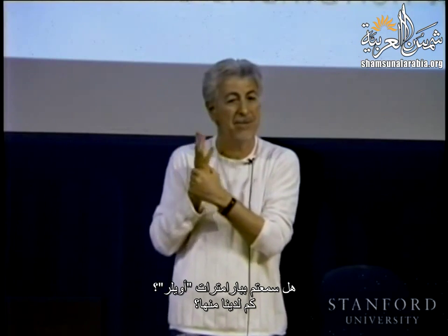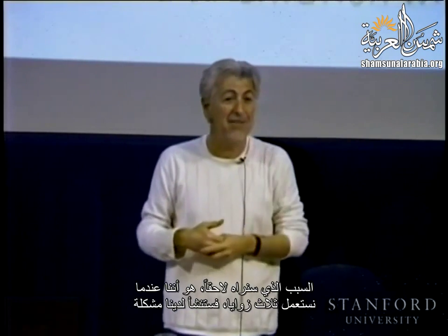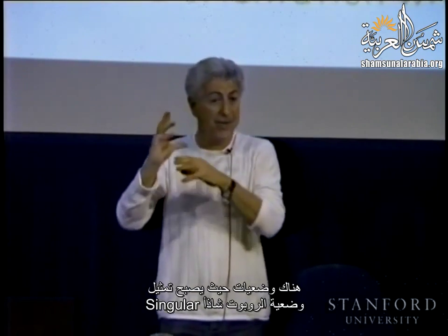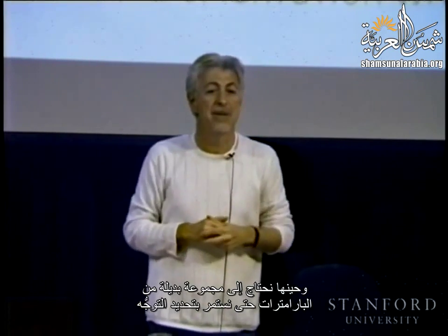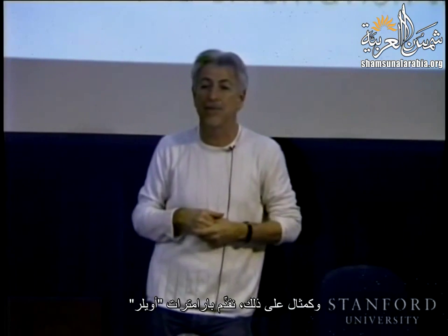Well, we will see also that, have you heard about Euler parameters? How many of them do you have? 4. So quaternion. The reason, we will see later, is that when we use 3 angles, we have a problem tracking this rotation continuously. There are configurations where the representation becomes singular. And we need a different set of parameters really to keep track of the orientation, and we introduce Euler parameters.